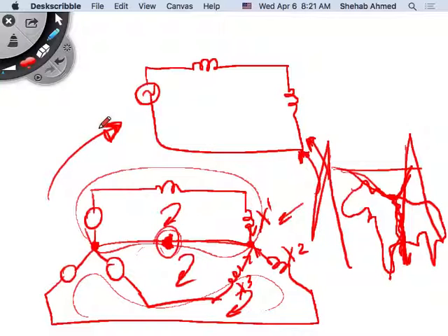So I will figure out how to model these components when they are unbalanced, such that I consider the fact that I have neutral currents, right? And in doing that, I will come up with models that will look like the single-phase equivalent circuits that we've been using before, so that I can simplify the analysis and still do it by hand for a small system quickly. Or if you're going to do it with a computer, you can do it a lot quicker, right?